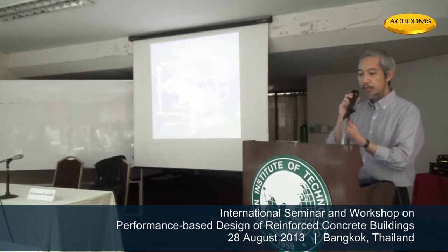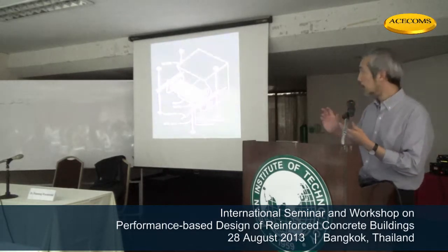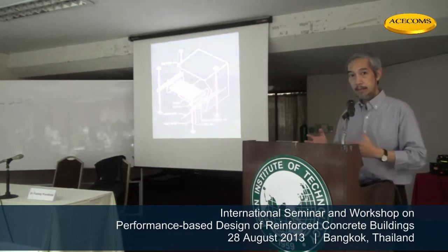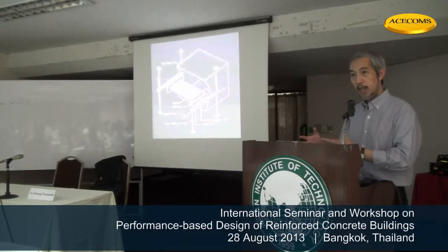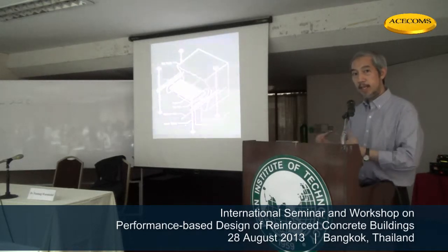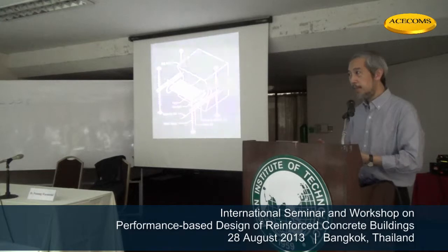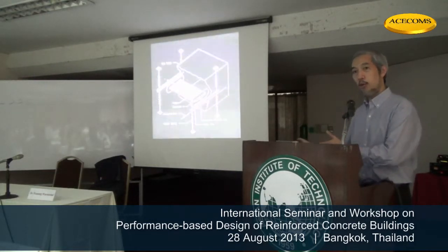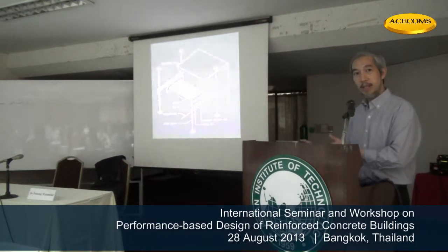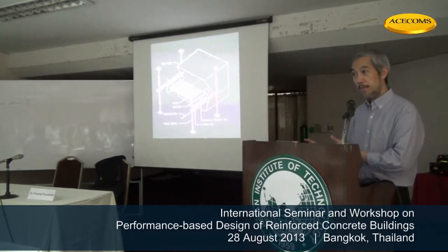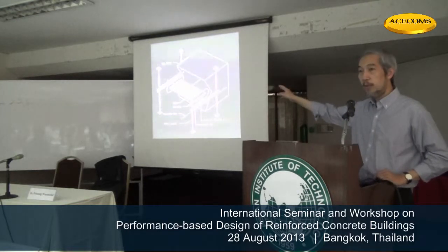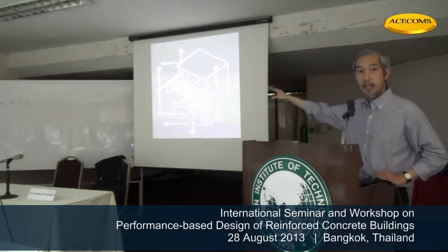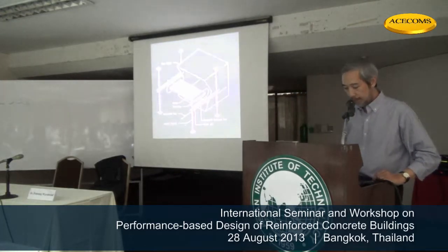And these days we can make a small model of the bridge and test it in a wind tunnel. It's a laboratory that simulates wind flow. And we can check whether this bridge will become like Tacoma, become unstable in the wind, or will be stable. Okay? It is possible to conduct this type of test to check the stability of the bridge girder. Alright?